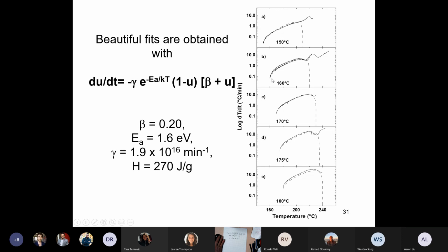And it's very useful to vary the mass of the sample, because sometimes you don't get to see all the features like this. What we would do is reduce the mass of the sample, and then the total temperature rise would turn out to be less because there's less reactants in the tube. Not only do you have to heat the contents of the tube through self-heating, there's also the stainless steel container that you also have to heat.